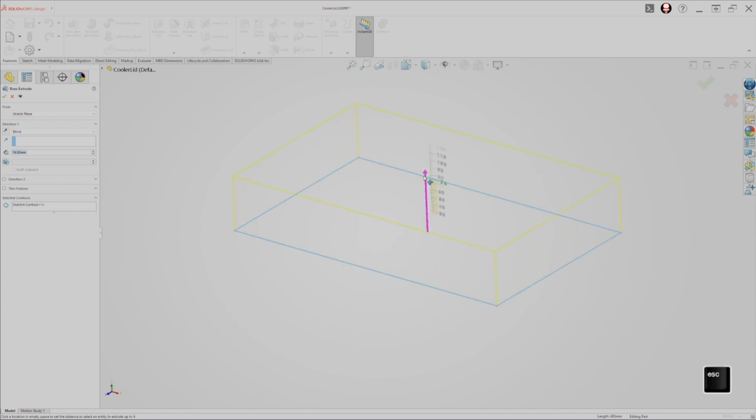So you could grab the arrow and move it up or down. I usually only do this if I'm designing a prototype and don't yet know the exact height. For example, I might have a sensor off to the right and use the arrow as a preview to see how much height I need to clear that sensor. So I'd want to make sure that the height is past the sensor, so I use the arrow to drag up and down to a good area. Then I will usually enter a nominal number afterward.